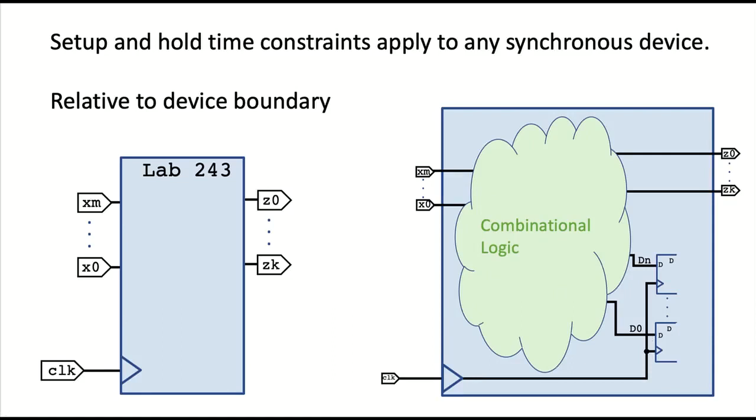In fact, if you go look at the data books for the Xilinx chips, you'll see that they have a negative hold time. But it's in reference to when the clock hits the edge of the component, the logic block, not the actual flip-flop.